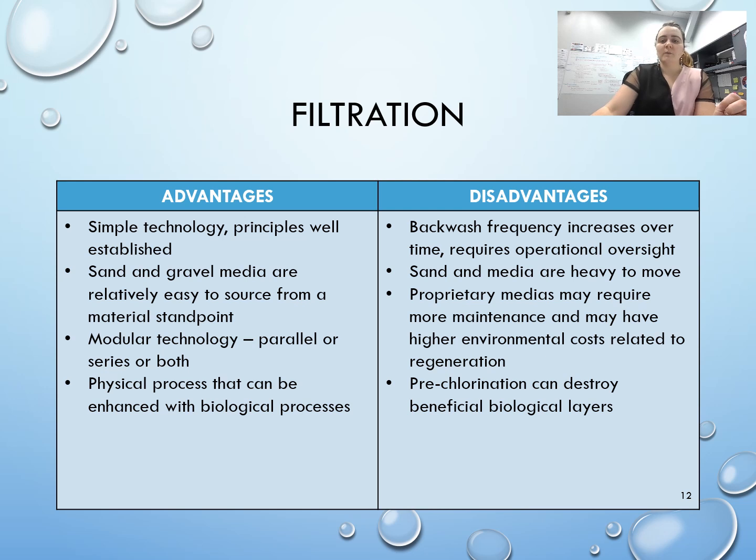And then if we do want that biological layer to be there, if we're pre-chlorinating and certain chemicals are too high before coming into the filter, we can actually kill that biological layer, and that's not a good thing. So we have to be aware of what pre-treatment we're using before filtration, especially if we care about that biological layer.